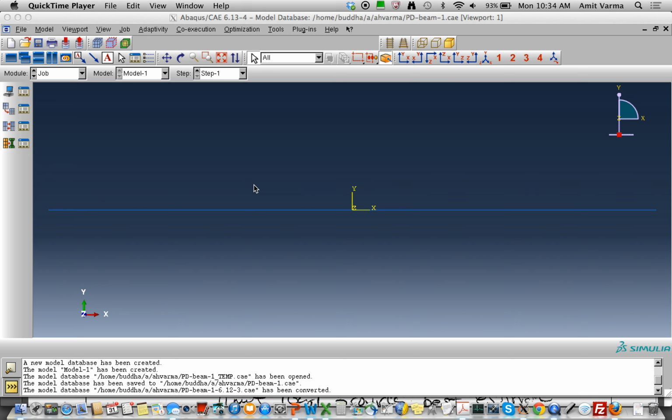Now, where would I get the bending moment diagram and deflections and rotations from? Do I have to solve this by hand? Well, I can find it in my AISC manual. As you know, there are tables there given for all different kinds of loading conditions and so on. So if I was ever hard-pressed to find the exact displaced shape for little v or little theta or the bending moment diagram, I'd have to just open my AISC manual, turn over to the tab that shows all the bending moment diagrams, equations, and I'd be able to find it.